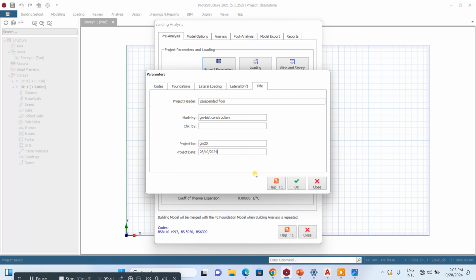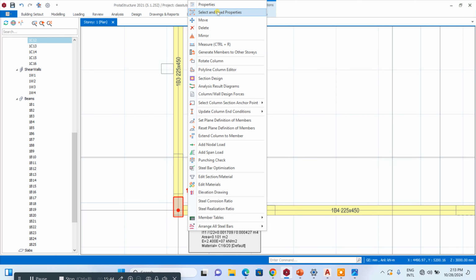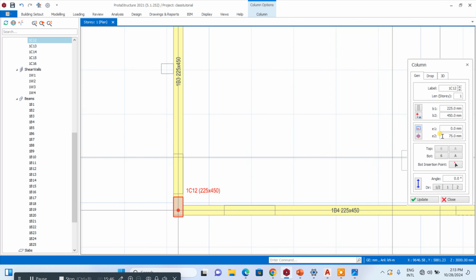You see positioning exactly at the edge of the beam. So also have a long length here. You can actually change this one to 450. You can either move it manually or using your arrow key, or you can just click on property, change this one to 112.